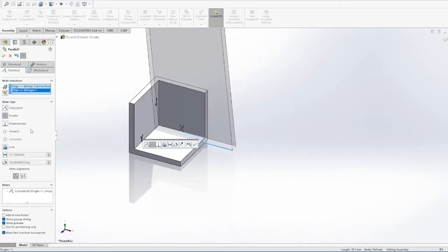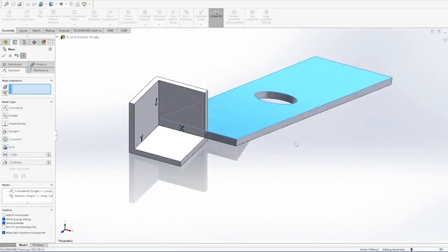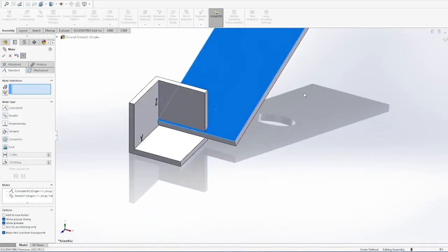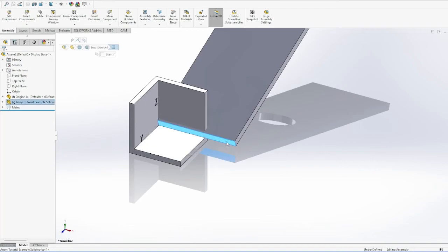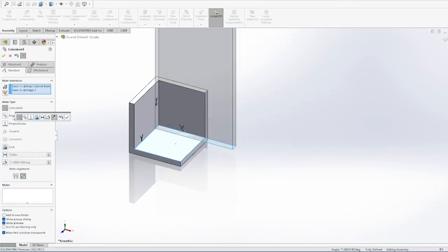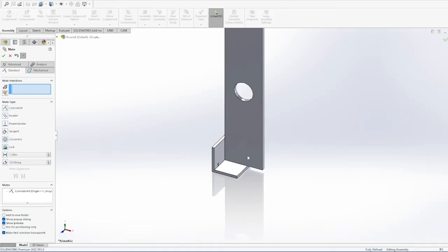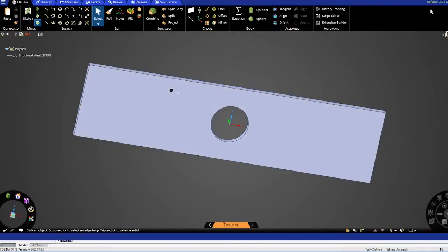Then what we'll do is we'll pin one edge, and what that's going to do is it's going to make it possible for us to basically lock that corner down. But it will mean that our system will freely rotate about the axis that we just pinned. Finally, what we'll do is we will pin the bottom edge to the bottom of that surface. And the benefit of doing these two basically parallel mates and a fixed mate is that there's no extra stress added to our part when it's under loading. And so this part is now fully defined, it can't go anywhere, but it also doesn't have to worry about any additional stresses as a byproduct of its construction. So we're going to do the same thing in Ansys, so I'm just going to tab over there real quick.